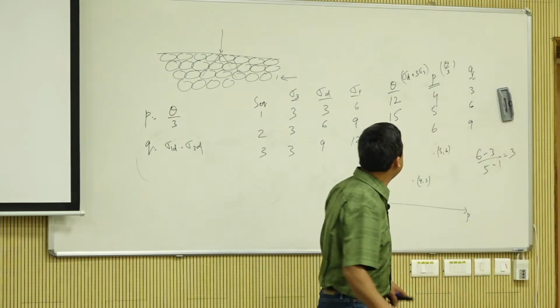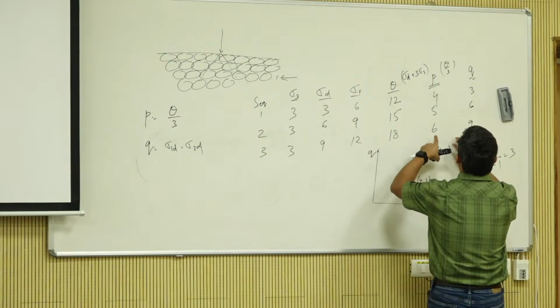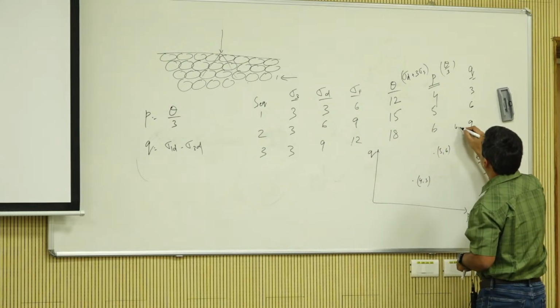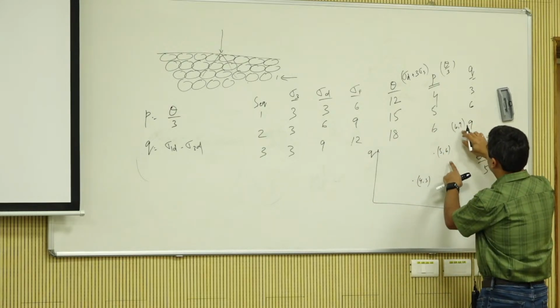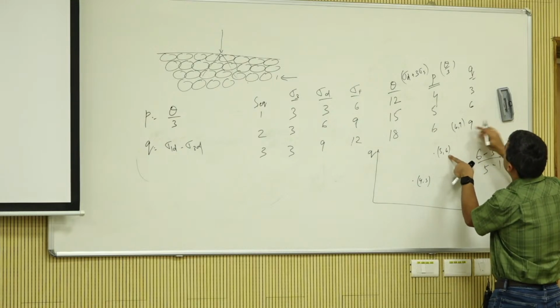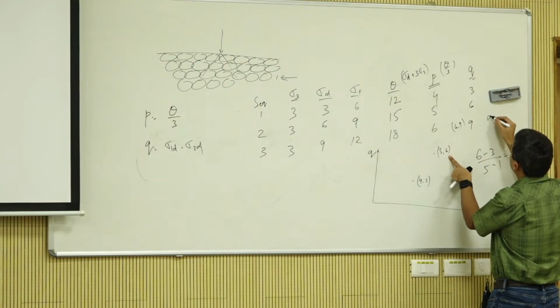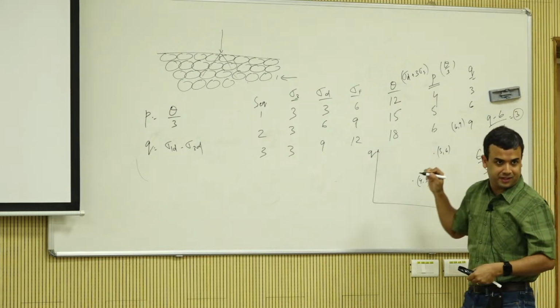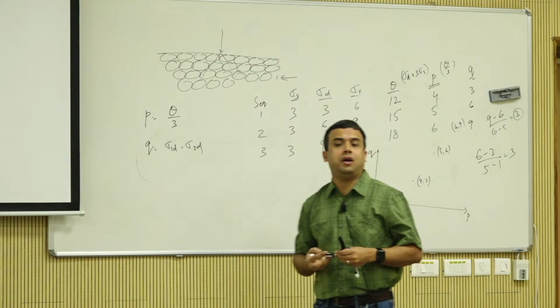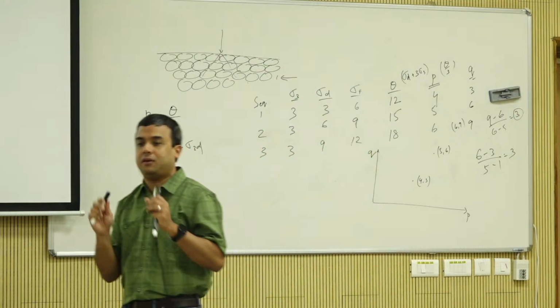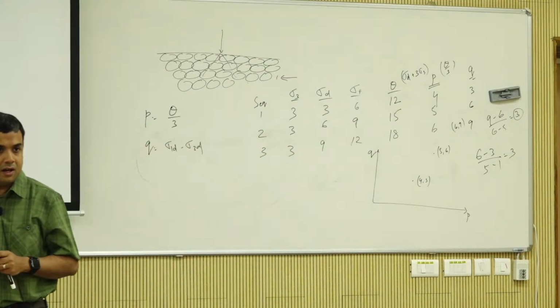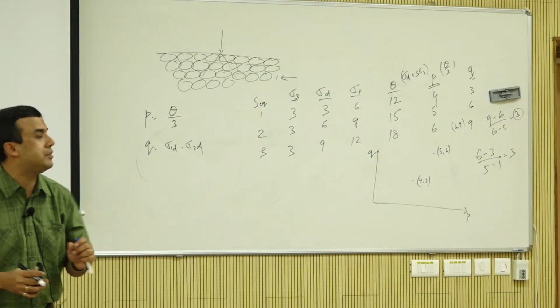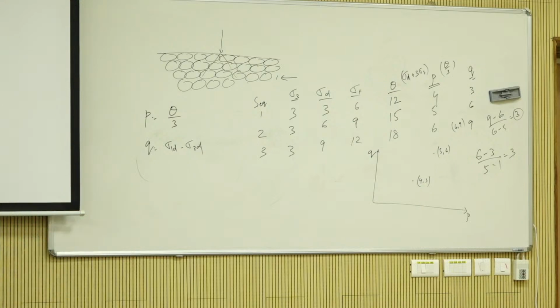Now let's go to the next stress state. What is this? P, Q is 6, 9. So it's 6, 9 somewhere here. Okay? So what is the slope between here and here? 9 minus 6 divided by 6 minus 5 is 3. So your traditional triaxial or resilient modulus testing on a PQ plot, your test slope is 3:1.